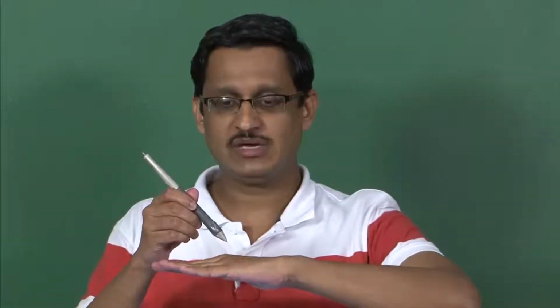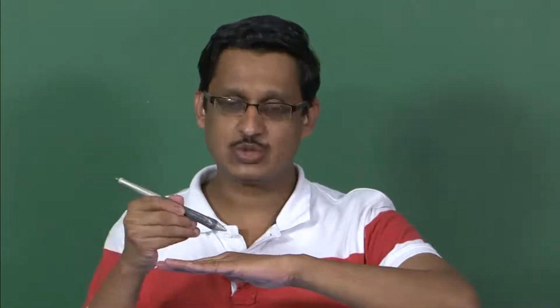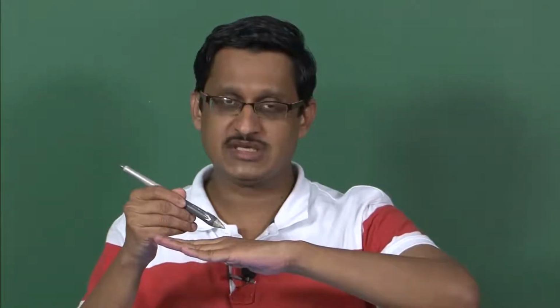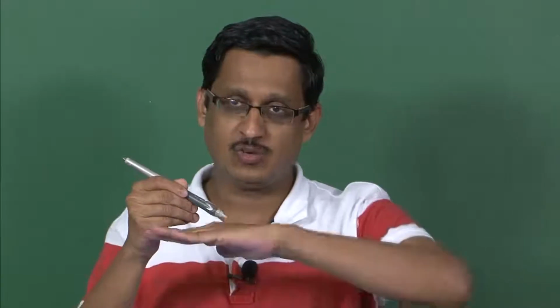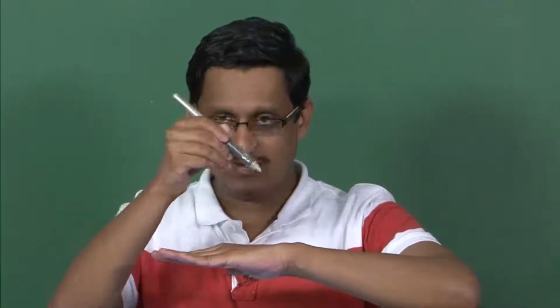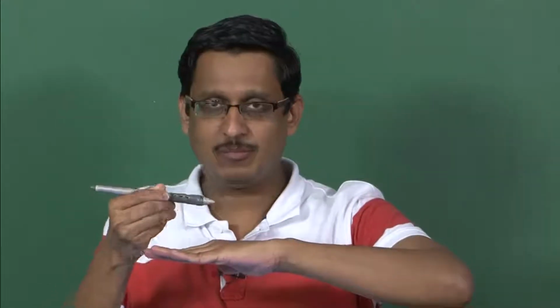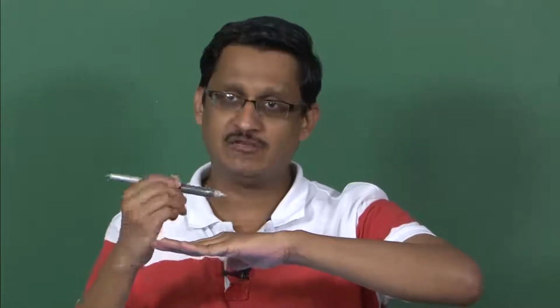So if this is the optical waveguide, you have a prism over here. There are a few considerations in choosing the gap, but the gap has to be chosen such that it is not very far or not very close, but an optimum gap. Then have light incident into the prism, and arrange the prism to gap boundary to be a total internal reflecting boundary.